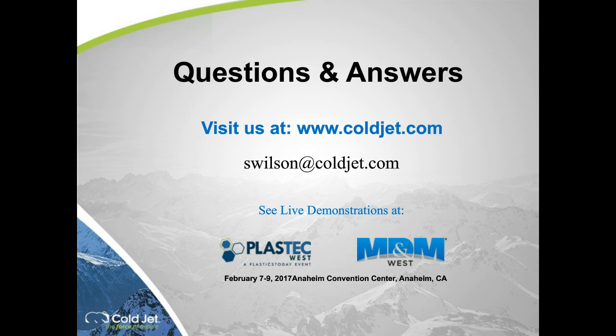Here's a good question. Can dry ice clean rust on water channels of mold? Yeah, it'll take, once again, dry ice is soft. This is one of the limitations and one of the nice things about dry ice all at the same time. It will take surface rust off. I see most guys using it to get the surface rust off of back plates. They're usually incorporating magnetic mold clamps, and they want that back plate to be as clean as possible. I'll take the surface rust off.